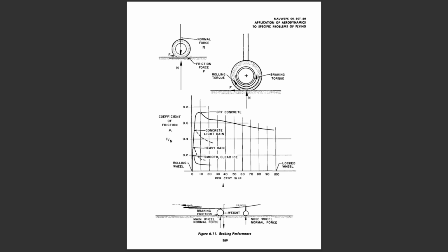During this portion of the landing roll, the pilot can control the airplane lift and the distribution of normal force to the landing gear. First to consider is that any positive lift will support a part of the airplane weight and reduce the normal force on the landing gear. Of course, for the purposes of braking friction, it would be to the pilot's advantage to create negative lift, but this is not the usual capability of an airplane with the tricycle landing gear.